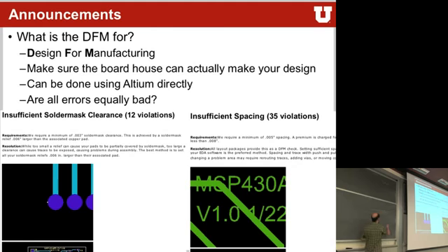Yet again, sometimes this effect is actually needed. For example, for BGA type of devices, which are ball grid arrays, where you have the chip, and on the bottom of the chip you have a lot of small little solder dots. There you actually want something like this, so that these solder dots go on top of the solder mask, and it helps them to align and stay up on top there. But most of the time, this is not what you want. So that's why FreeDFM tells you, well, your clearance is so close, you basically went right to the edge here, that we can't guarantee that we don't go on top of it. They need a clearance between your copper that you have here and wherever the solder mask should stop.